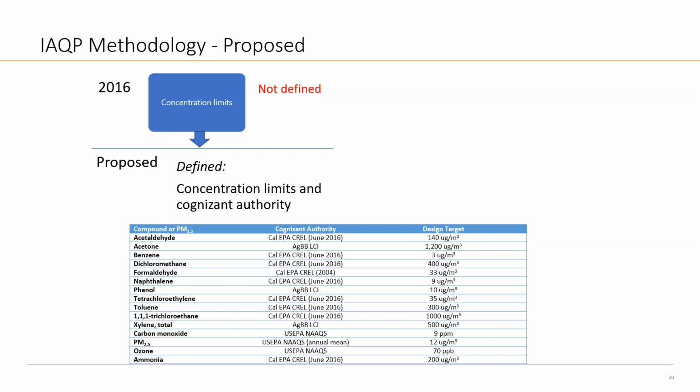Unfortunately, you cannot include CO2 in this addendum because you will not have a limit from a cognizant authority, and these are all health-based limits. So you can definitely only use it for VOCs. You need to calculate carbon dioxide and see what the impact is, and maybe share it with the engineer and the client. I encourage you to add carbon dioxide to your list on top of this and justify it, because you can't include it in the text of the standard without a cognizant authority.